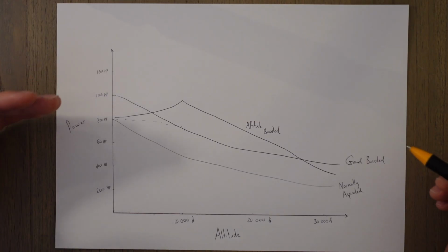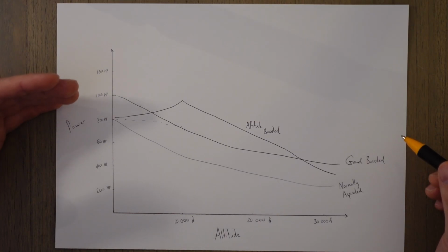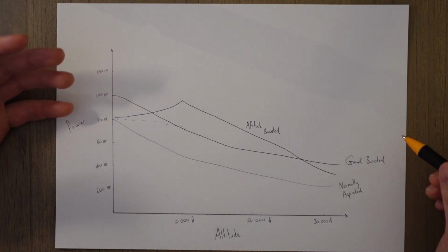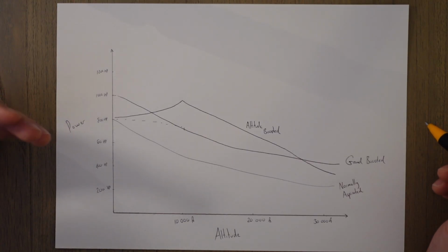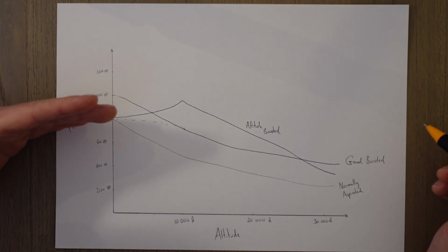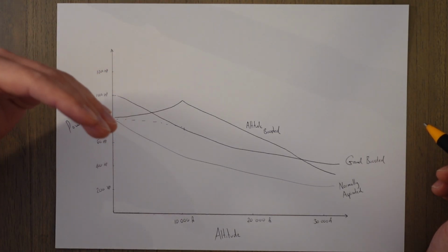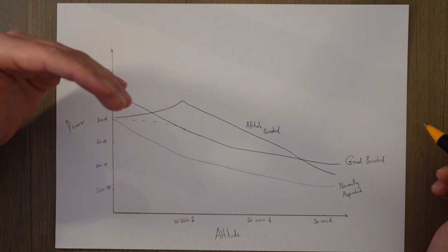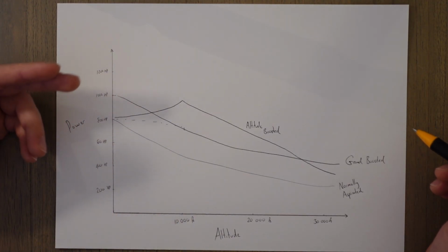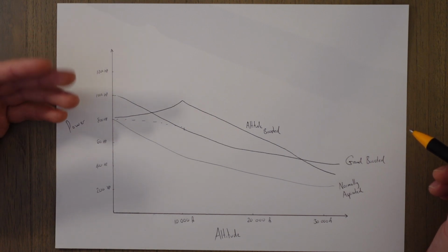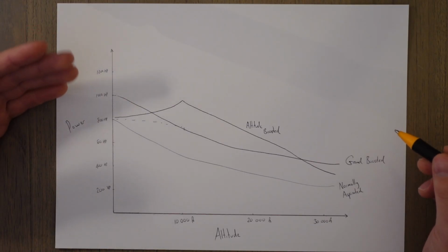The other way is called altitude boosting, whereby the supercharger is tuned to a specific altitude so that it provides its maximum boost and power increase at the rated altitude. This means that the amount of boost slowly creeps up as we reach the altitude, then it drops off in the same way as both the ground boosted supercharger and normally aspirated engine do after that point. This means that it can be tuned for a specific cruise altitude, engine RPM, and other various factors to provide the most power for cruise, for example.